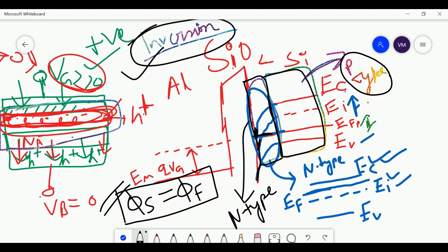In the later stage when you study MOSFET, you will be able to understand that this is the reason why NMOS and PMOS are able to conduct current between drain and source. Fine. So this was an important condition, the third condition of inversion. So we have studied the three conditions of operation of a MOS structure, that is accumulation, depletion and inversion. Now let us come back to the second condition, because in the second condition we have an important derivation.